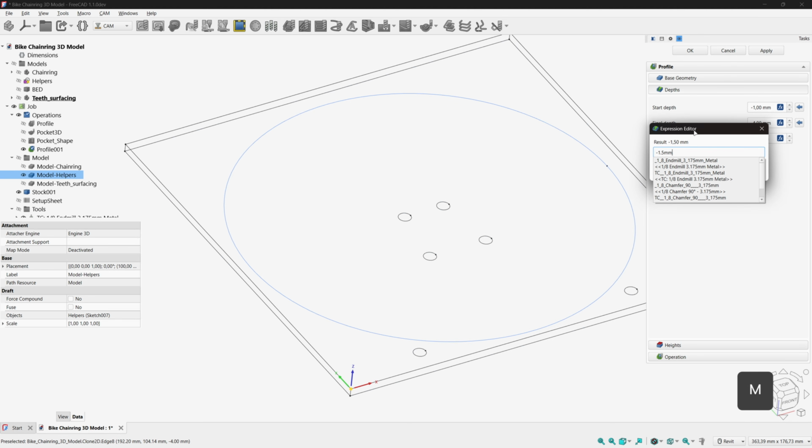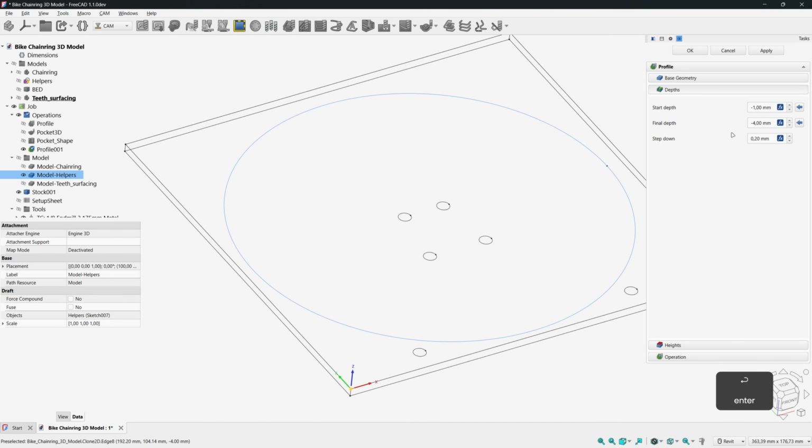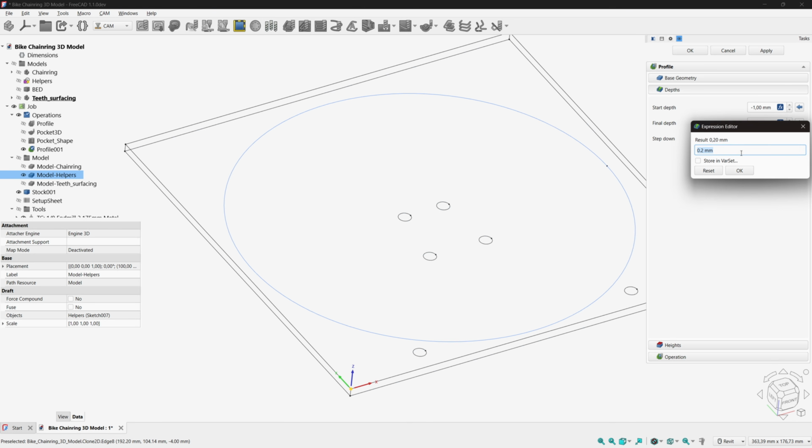Since the chamfer is very small and our bit can create a maximum chamfer of 1.6 mm, we can just do a single profile operation and step down gradually until we reach the chamfer depth of 0.5 mm. If we wanted a 4 mm chamfer, for example, we'd need a larger bit or another technique, which I'll show you later. Next, in the step down, I'll change the value to 0.1 mm. This gives a better surface finish and a clean result with the chamfer bit I'm using.